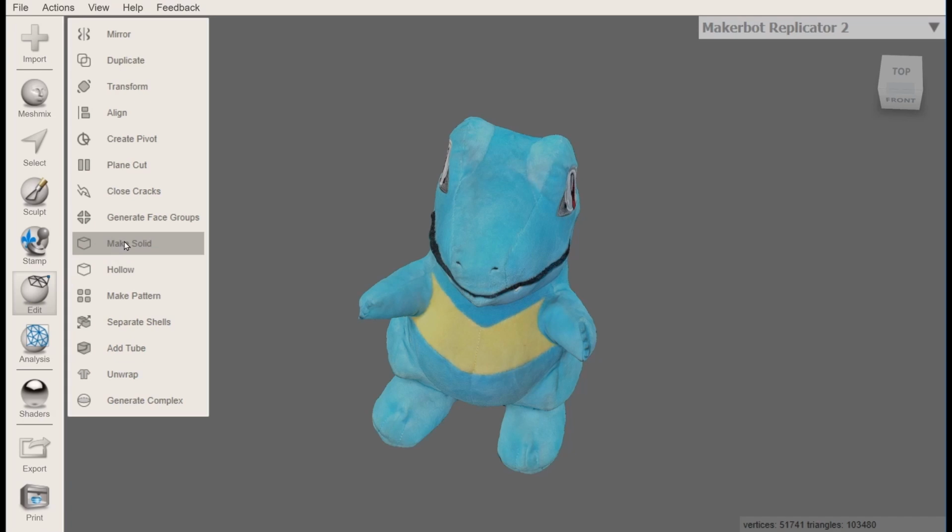I mentioned a little bit in the previous tutorial how digital products don't need to be solid because they can have exposed polygons, and even though it's not good practice, it isn't going to affect how they work. Whereas with 3D printing, the object itself needs to have every polygon closed. So what does that mean? It means every edge of a polygon has to touch another polygon so that it's entirely closed.